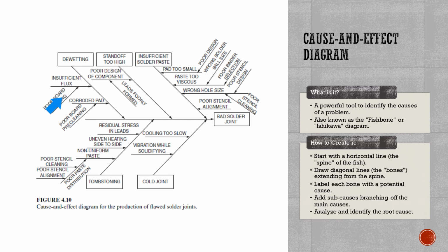which contribute to the wetting problem, such as insufficient flux, poor board cleaning, for example, and then corroded pad, which is poor board pre-cleaning.